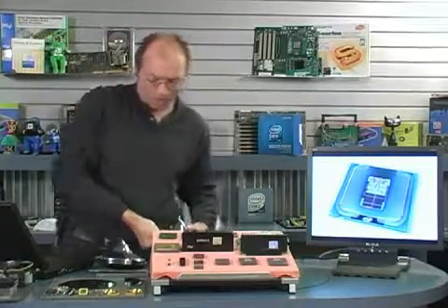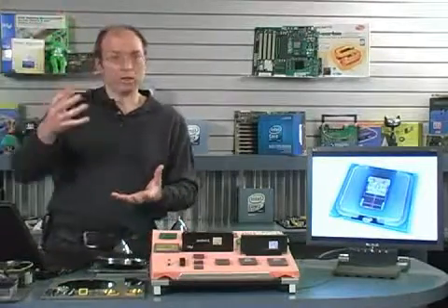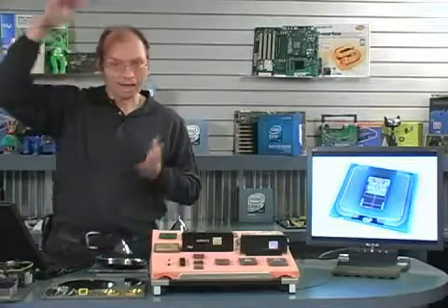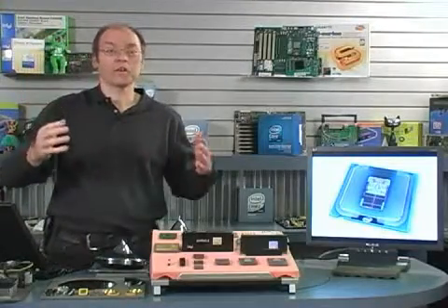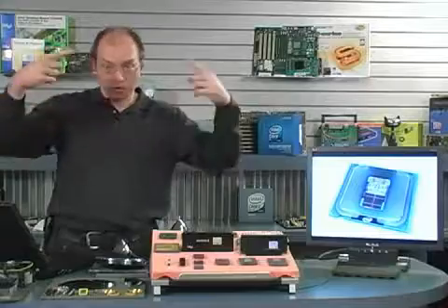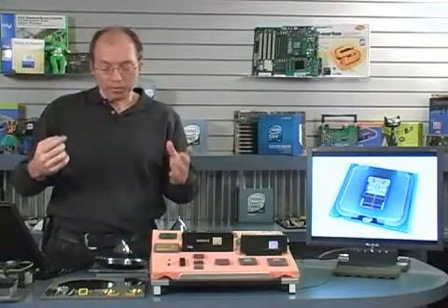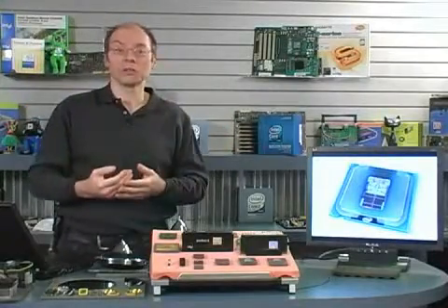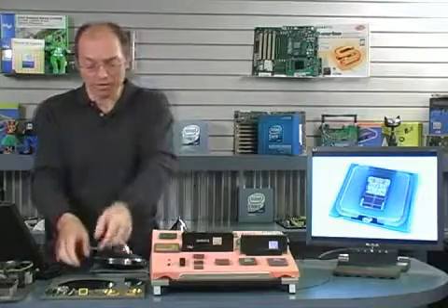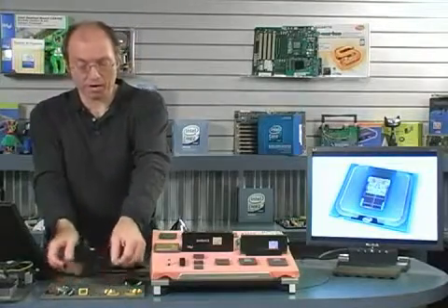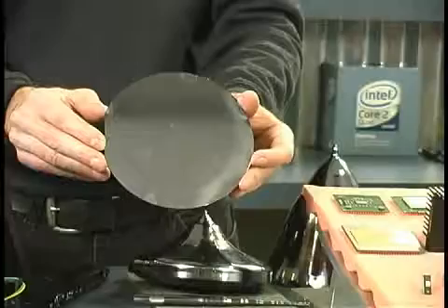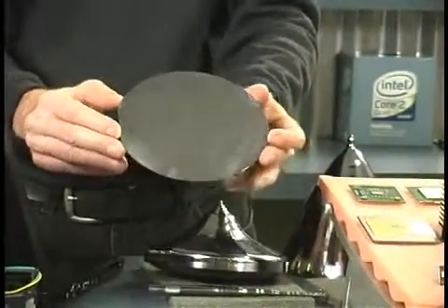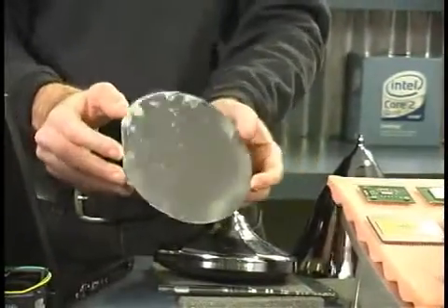So now what we have is this cylindrical crystal of silicon, with head and tail cut off. It's ground so that it's perfectly round, and then it is put into a saw that cuts it into thousands of plates called wafers. I have an example here of a wafer that was cut from one of these crystals. You can see that it's round and is very thin.